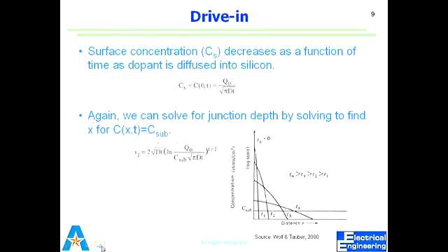If you look at a plot of the dopant profile, that should tell you right there if this is a diffusion process or an implantation. Because implantation would have a Gaussian with trailing ends on both sides. But in the case of diffusion, this would be the source-limited form, where the profile will just become flattened with time.